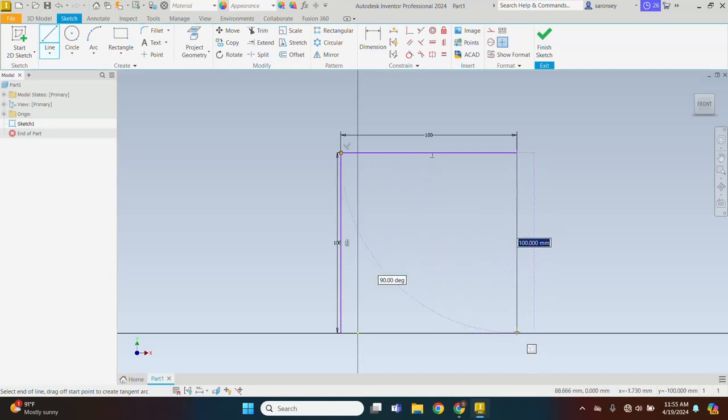You know the line is straight when the line is not broken. And then also notice that small perpendicular icon there. It tells you that the line or the point you are at is perpendicular to the horizontal line passing through the origin. So you can click there also, and then finally you can close it by moving the mouse to click on the point where you started.